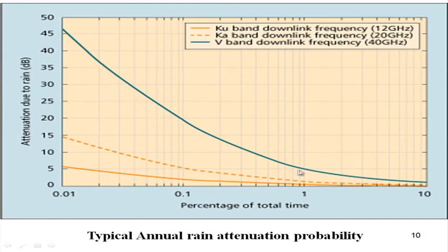For a longer duration, the bursts of heavier rain for short durations are all accumulated together, so you can have a lower attenuation. So, your quality of service, that means how much time I can give a guaranteed service that my system will not fail, will not go below the signal to noise ratio or carrier to noise ratio level, you can determine, and accordingly that much attenuation you should protect against.